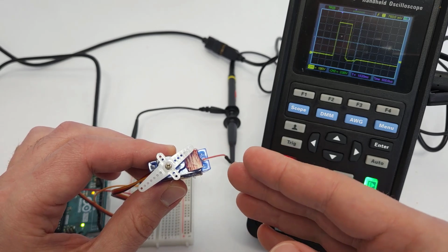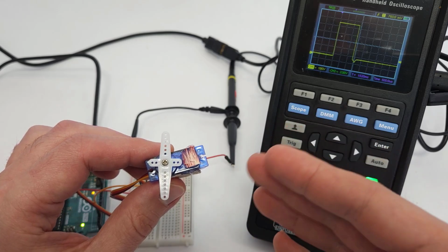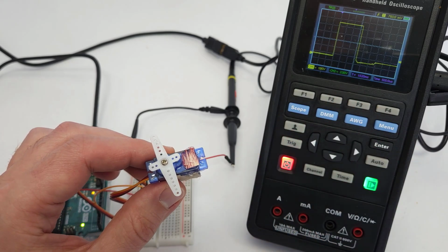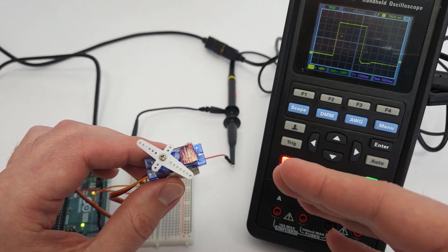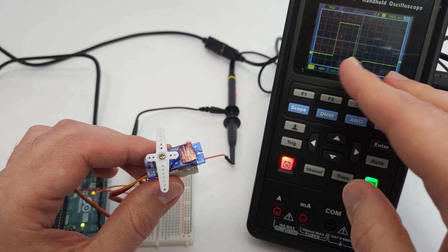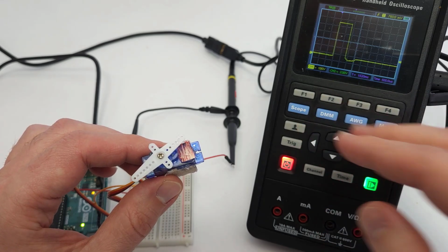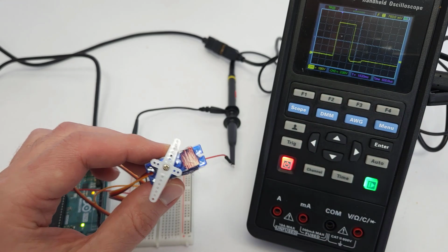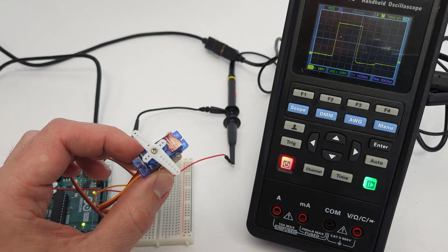That could be fine for a mechanism where I only need the servo to oscillate between, say, 0 and 90 degrees. But if I need finer or more accurate position control, then I would need to do that with the 16-bit timer myself, doing it manually with the registers as we saw. Same process, but you would need to look up the different registers for timer 1 in the datasheet, or you could use the Arduino Servo library.